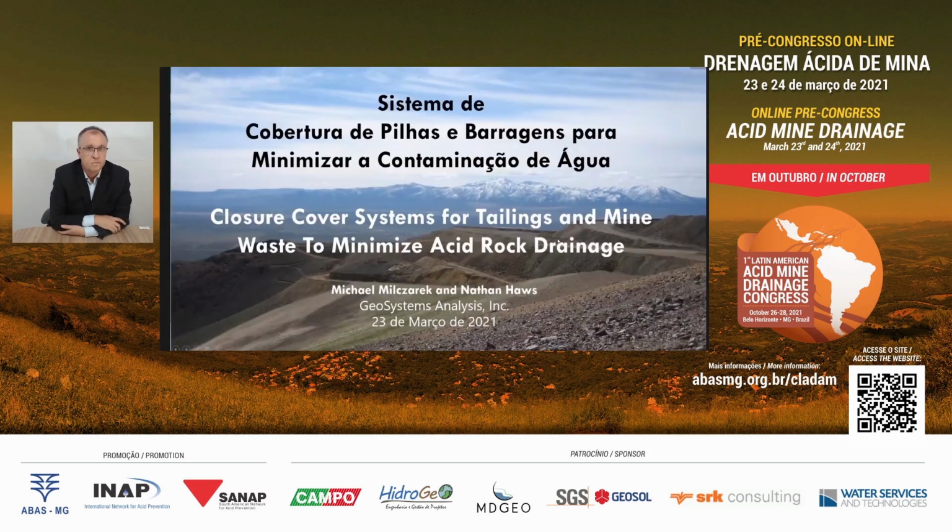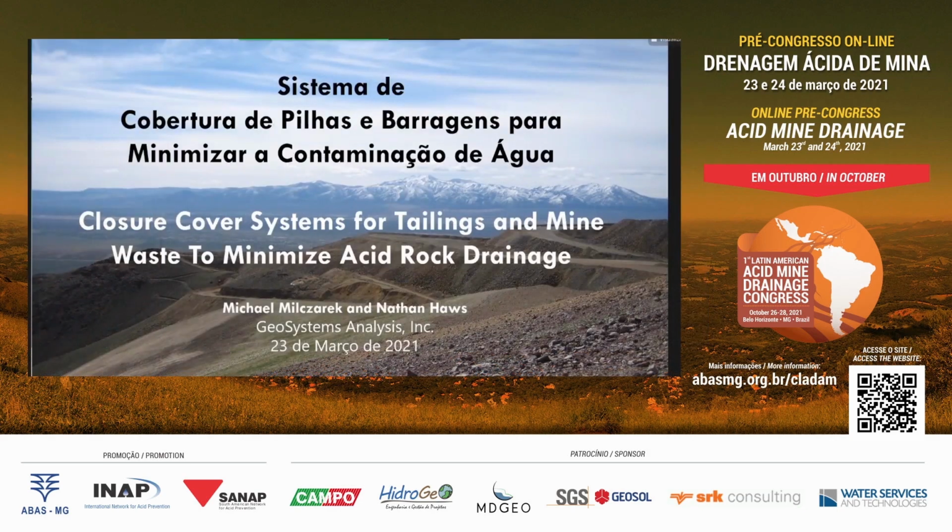Yes. Okay, perfect. So today I'm going to provide an overview discussion of closure cover systems to reduce infiltration into waste rock and tailings and hence minimize acid rock drainage. I won't be providing any specific details as to how to design cover systems or how to characterize materials. I'll be giving a workshop with Flavio at the next acid mine drainage conference in October, and we'll be providing much more detail at that time.